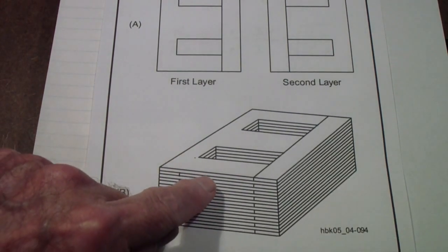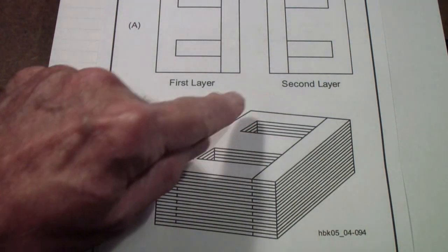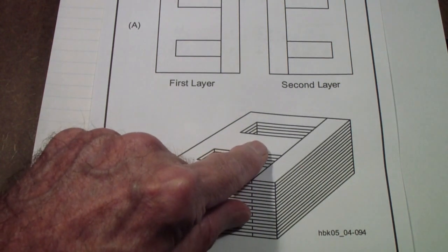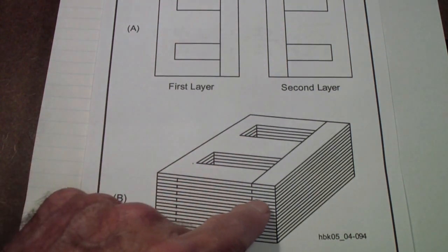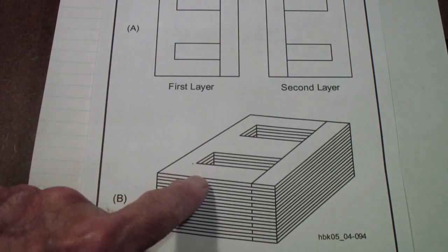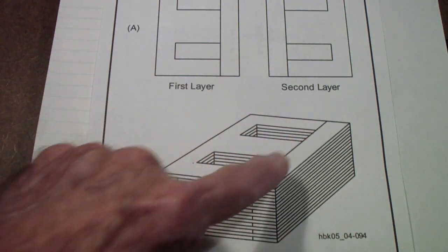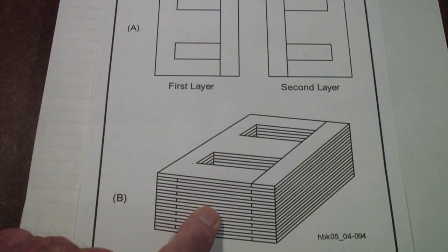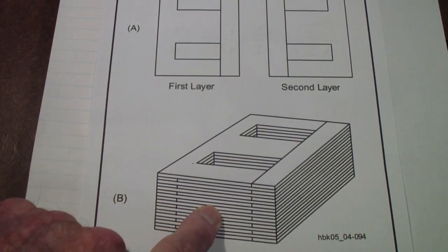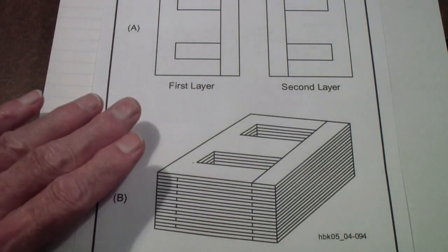the tendency is, of course, that the magnetic field in the primary induces not only current in the secondary, but also current in the core itself. And that current will travel around in circles here, and those are called eddy currents. They get worse as the frequency goes higher. So what they do in transformers is separate the core into thin sheets.